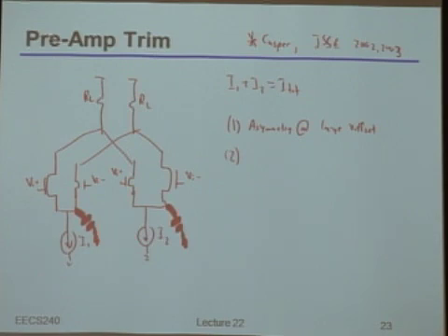The bias current, is that what you said? The bias current RO. Well, notice in this particular thing, it's not that I'm really taking a bias current and dumping it into the resistance. I'm actually just deciding how much of the bias current flows through this differential pair versus through this differential pair. Okay. So you said the range is the ratio of the big width to the small width. And it's basically directly related to that.